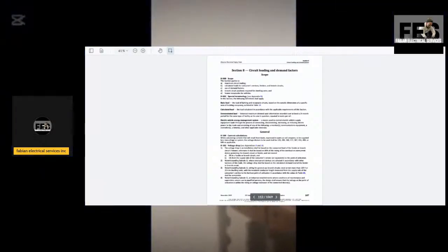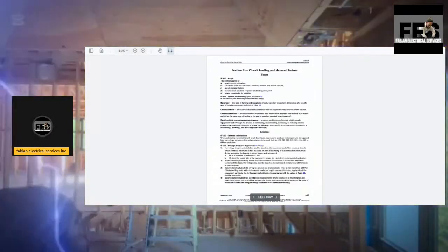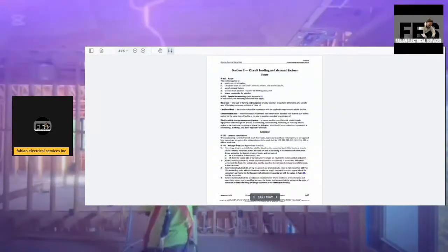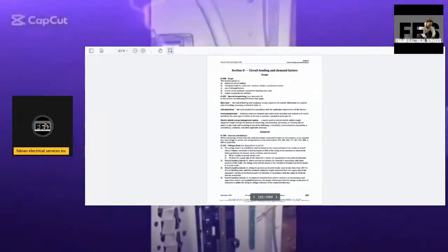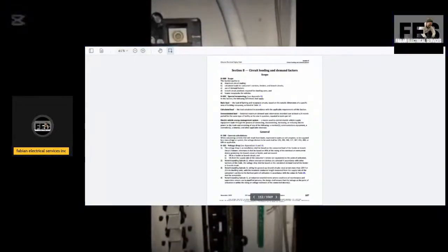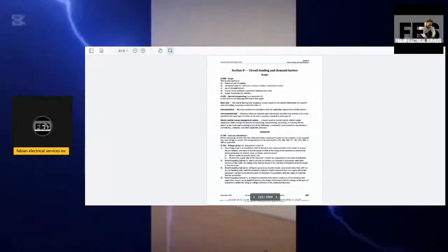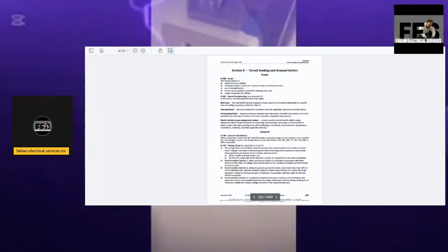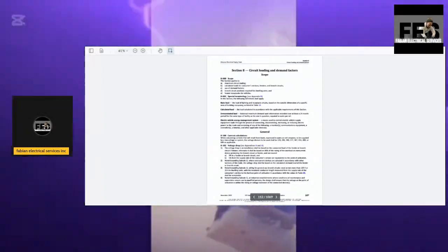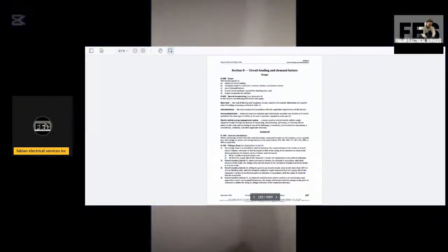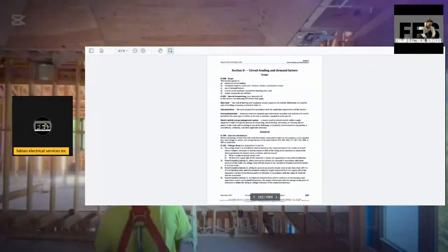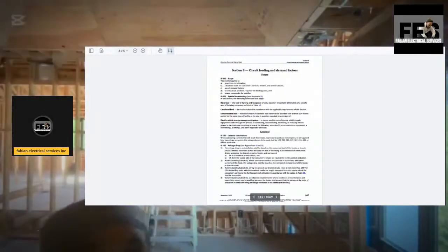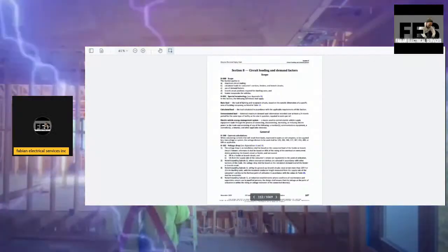We're just actually going to look at the voltage drop. I have dropped a rule on the voltage drop, and you see it's going to send you to see Appendix B and D. The voltage drop in an installation shall be based on the connected load of the feeder or branch circuit if shown. Otherwise, it shall be based on 80% of the rating of the overcurrent device protecting the branch circuit or feeder, and not exceed 3% in the feeder or branch circuit, and 5% from the supply side of the consumer service, or equivalent, to the point of utilization.